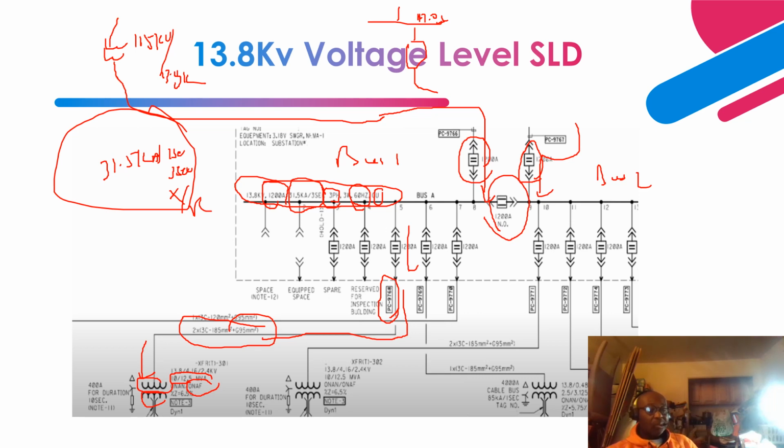So this symbol basically shows you the Y side, the low voltage side is resistance grounded, right? Okay, and basically to limit the fault current to a level. And the fault current level limiting is 400 amps, as you can see over here, for a period of 10 seconds, right? Okay, so that is basically I²T, the current and the time that corresponds to heating.